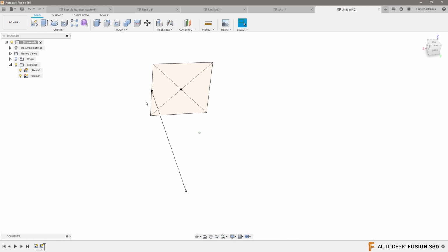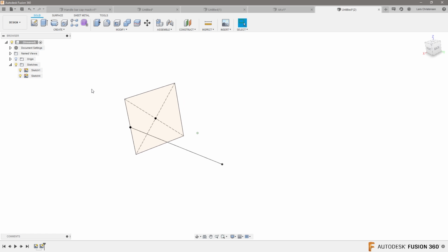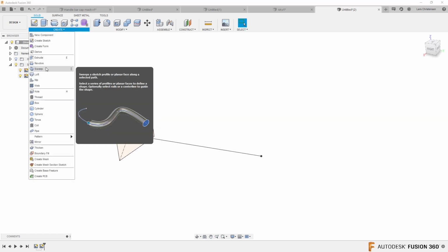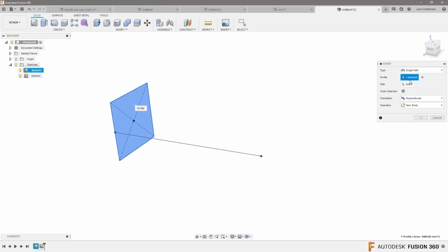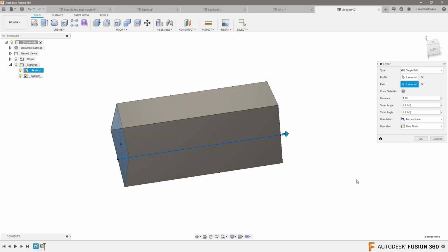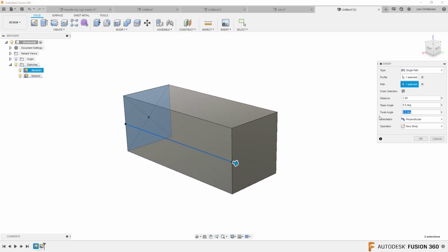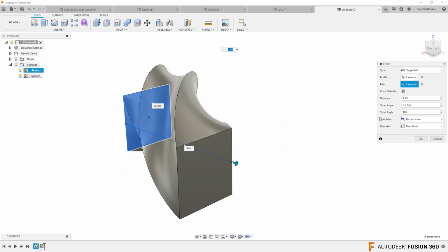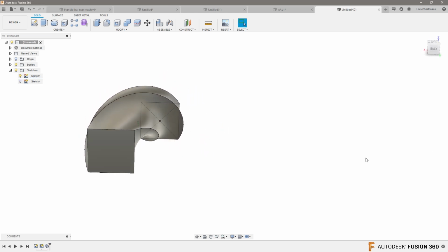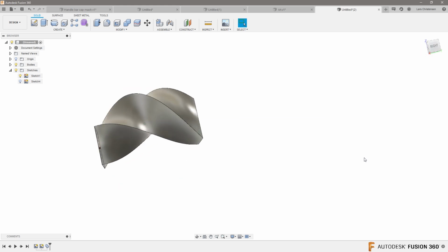You will now see that I moved the sketch line from the center. Well, maybe this is what you want. Now, if we're going to sweep this along this path, everything looks the same, and this is the same until we're adding our twist angle, and you will now see it's twisting over that line. So you just gotta be aware of that.